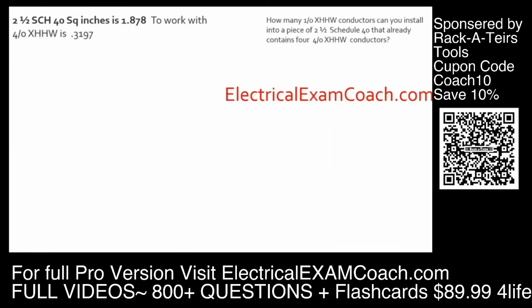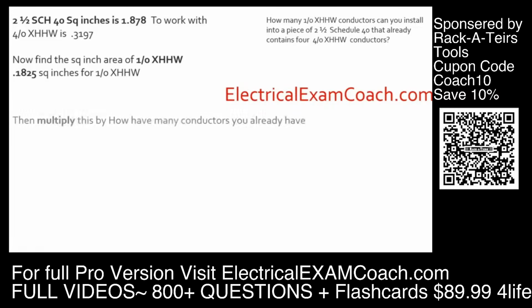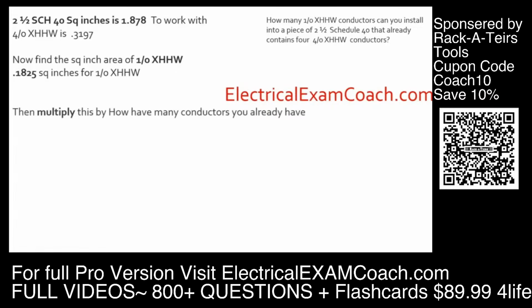Now that we have our conduit and our starting conductor, let's go ahead and write down what the conductor that we're wanting to install is. And it's 1/0 XHHW. Now we can start all over. We multiply by how many conductors that we already have. We have 4 multiplied by the value for a 4-aught, and that gives us this number.